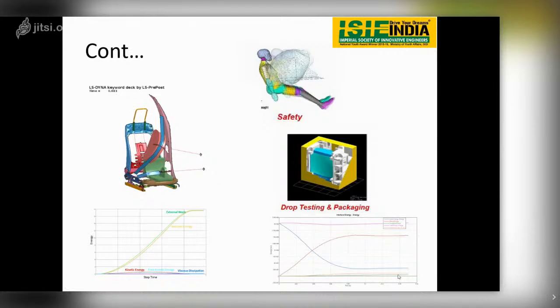That is because of less accuracy in defining the problem, or the mathematics, or the behavior of the particular element. Because of that, we can get the hourglass energy. But these two energies are well below the 5% limit, so that is not a big problem.